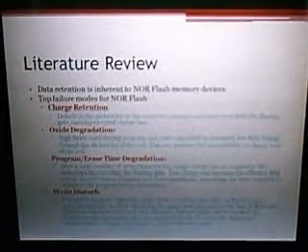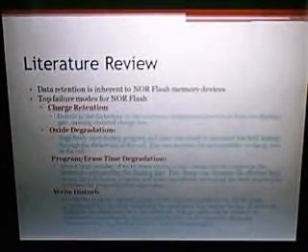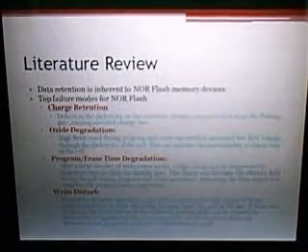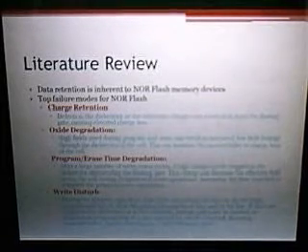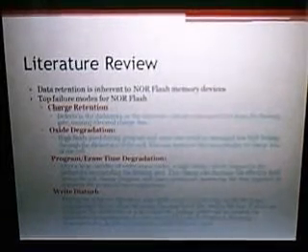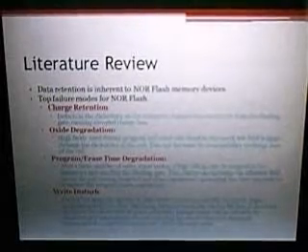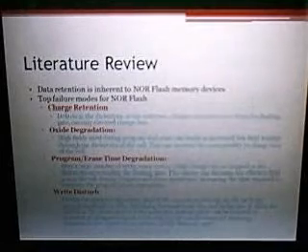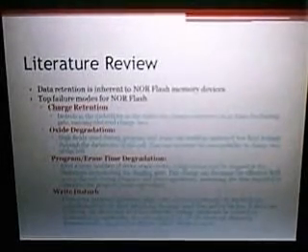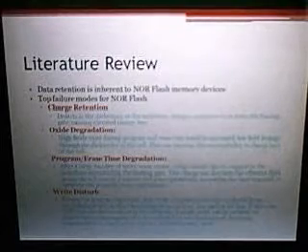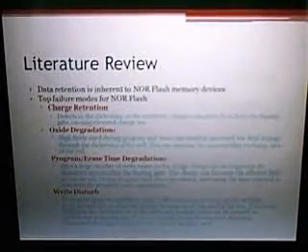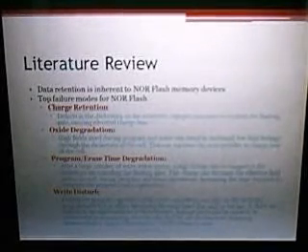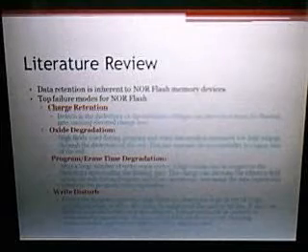We also found that a dominant failure mode within a NOR flash component is program erase time degradation. Basically, after a large number of write erase cycles, a high charge can be trapped in the dielectrics surrounding the floating gate. This charge can decrease the effective field across the cell during program and erase operations, thus increasing the time required to complete the program and erase operations. We can see that in this particular case, this failure mode is not applicable to the data set that we're studying here and the issue that company XYZ is experiencing.